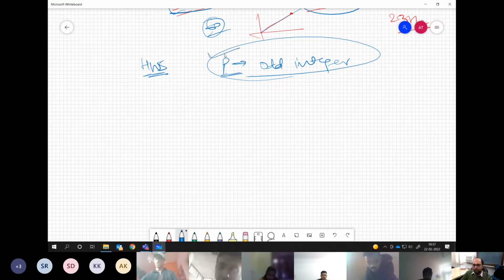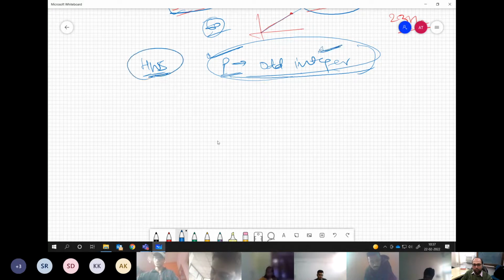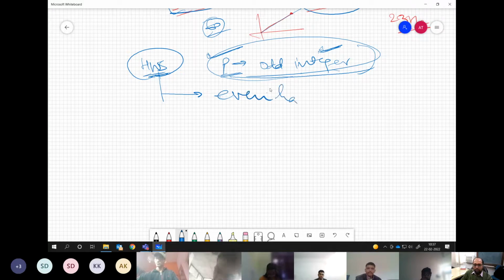So we have seen that pulse number must be an odd integer if we try to maintain half wave symmetry. Definitely if it is an even integer, you can never maintain it. Only if this is odd, you can have the possibility of maintaining half wave symmetry. What will half wave symmetry do? Eliminate even harmonics. Yes. So even harmonics would be missing from the waveform.